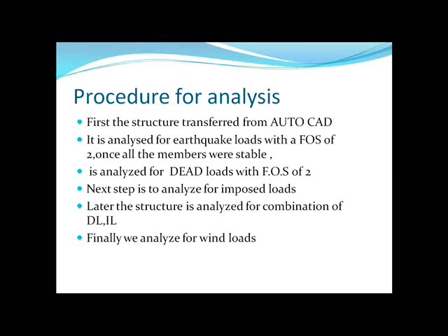And the procedure for analysis: first the structure is transferred from AutoCAD. It is analyzed for earthquake loads with a factor of safety of 2, and once all the members are stable, it is then analyzed for dead loads, then for live loads and then for the combinations.